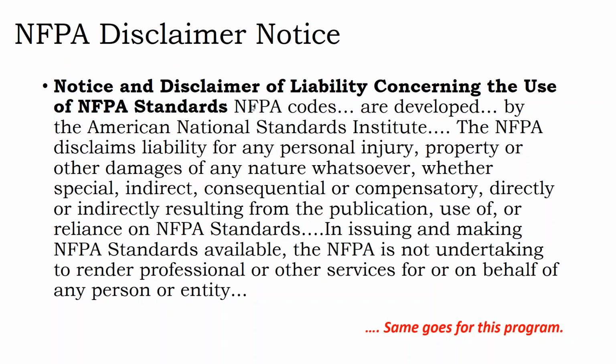Let's see. So I guess the last thing we have to do is disclaim liability. Code is a minimum level of safety. In fact, you're going to find situations where you say, I might be in a dry environment, but this room could get some water into it if there's a hole in the attic or something, so I want to design it like it's a wet environment as well. You can do that. You can go beyond the minimum standards of code, and electricians do it all the time in terms of upsizing their conduit, upsizing their cable.